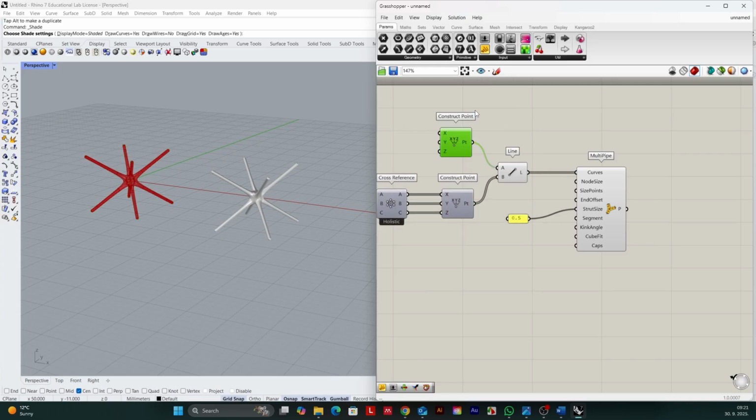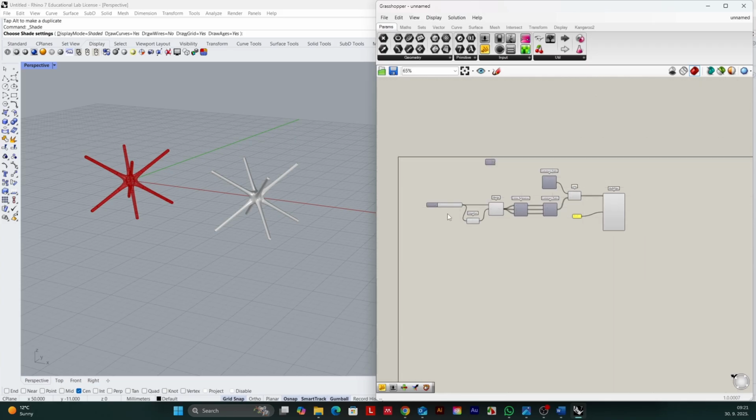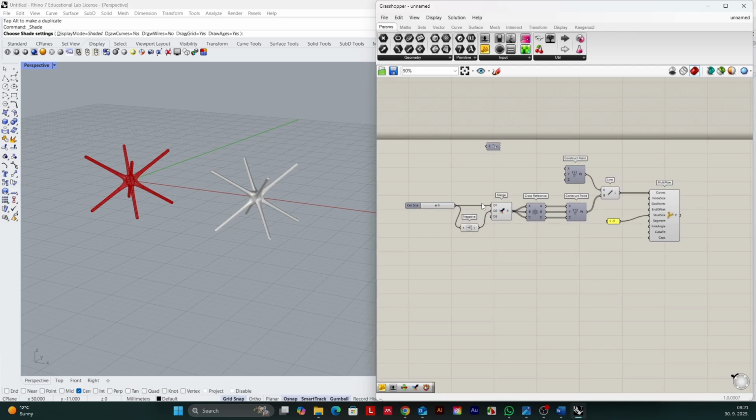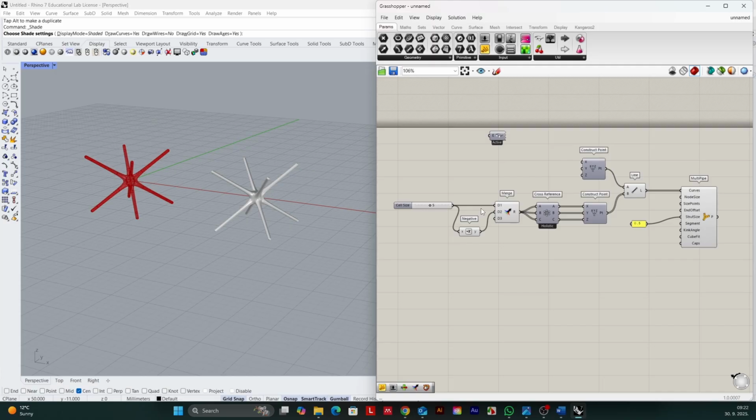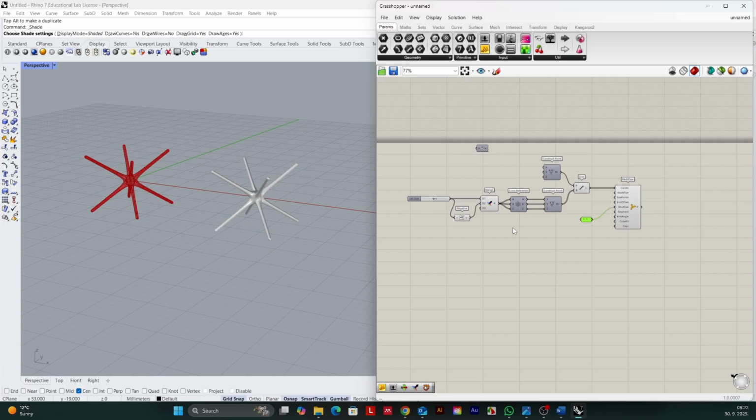So with this workflow in Grasshopper, we created a fully parameterized geometry for a unit cell named BCC, or body-centered cubic, ready for the next workflows to implement it into bigger and more complex structures like periodic uniform structures based on this kind of unit cell. That's it.